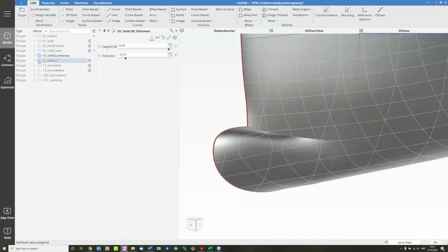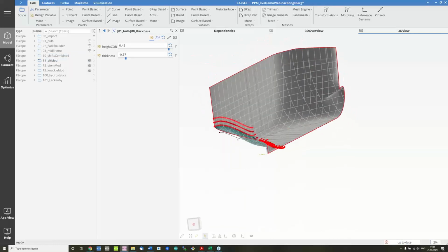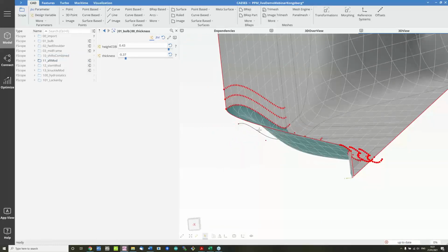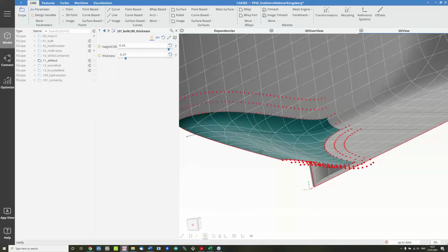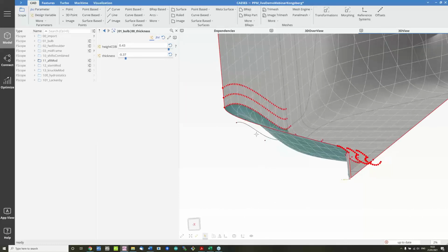I would now like to continue with some deformations that would not have been possible in our earlier versions of CAESES 4 because they use what we call BREP morph. That's a partial parametric modeling technique that is completely new, introduced in CAESES 5, and allows us to move geometry. In most cases, these would be BREPs, and match certain source and target geometries. That means we can set source and target points or curves or surfaces and tell the BREP that we want it to change in shape so that it would deflect and change from one shape to the other.